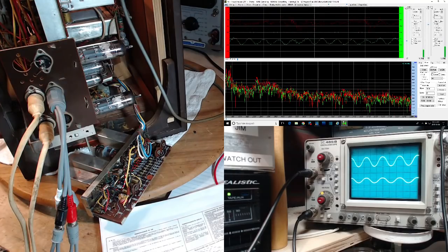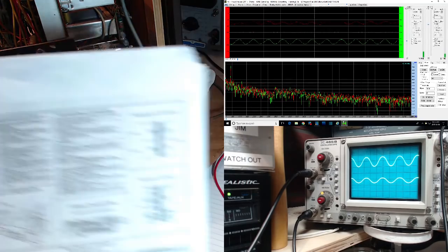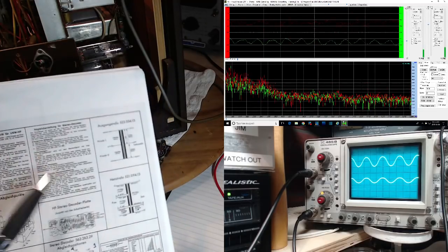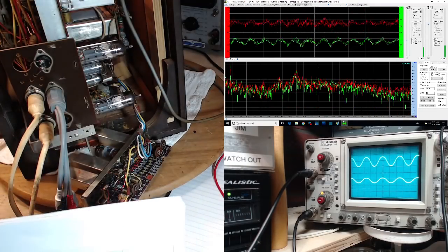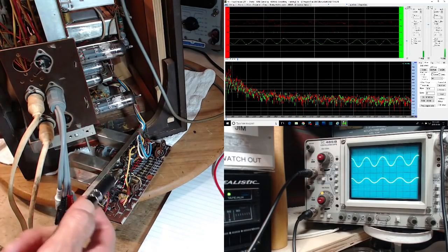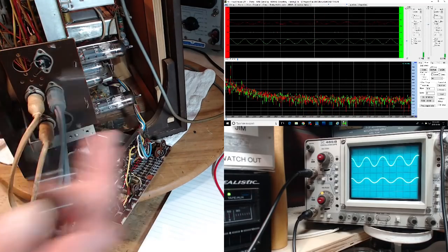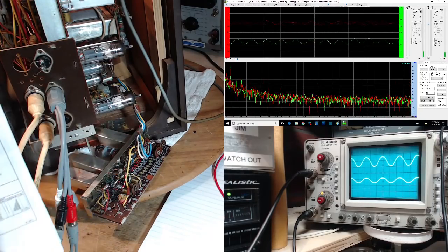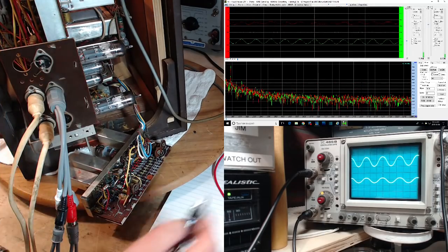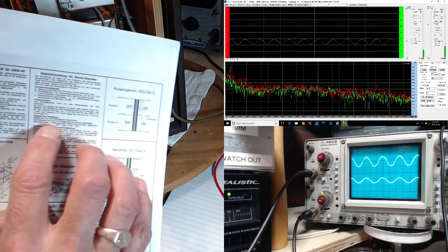Okay, so I read over the instructions as best I can, and it's not the greatest. The scary thing about this is there is an expectation that I'm going to feed a 7.5 kilohertz into the left channel, 8.5 kilohertz into the right channel. Somewhere down the line while making these adjustments, I'm going to find a 1 kilohertz different signal, and some adjustments are made based on the 1 kilohertz. I can't generate those 2 signals. I can't follow these instructions. They're in German anyway. But at least I've got an order to things.